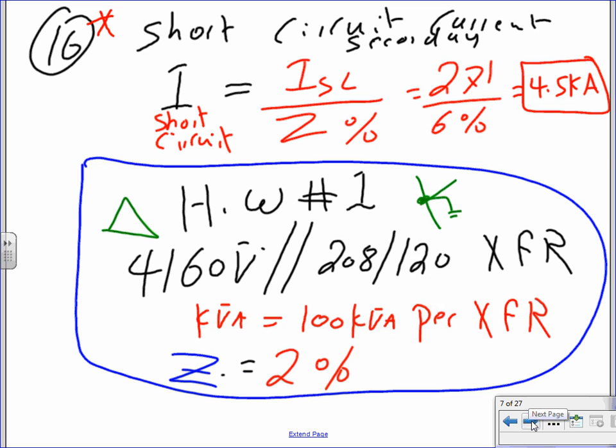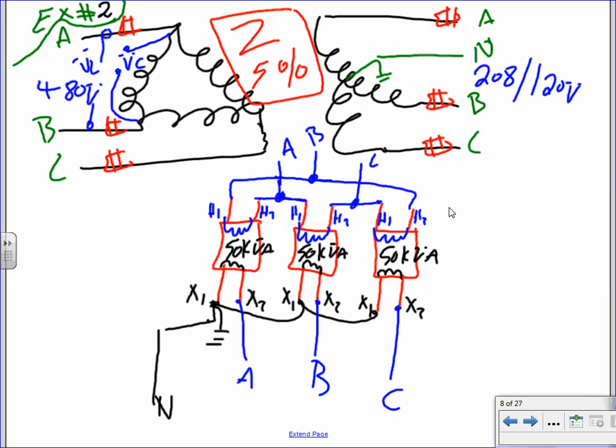That's all right. So you got the homework, guys. Let's go directly into the second one. You have a picture of this. I picked this one for you, Adam, for one reason: this one has primary and secondary voltages less than 600 volt. Can you guys see that? The primary is 480. The secondary is 208, 120. That's the reason why I picked this one.